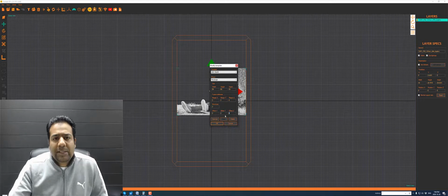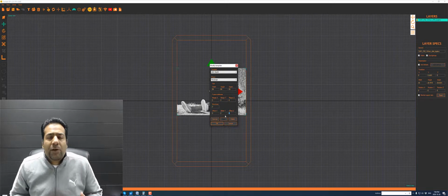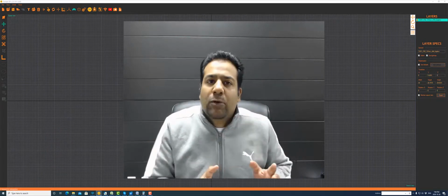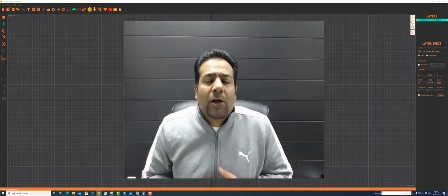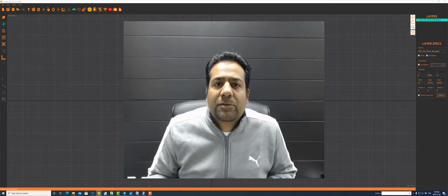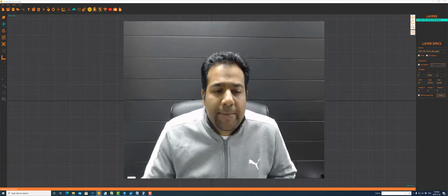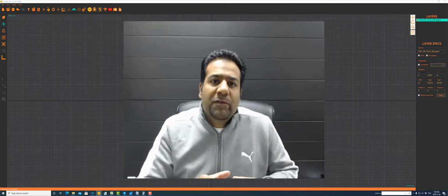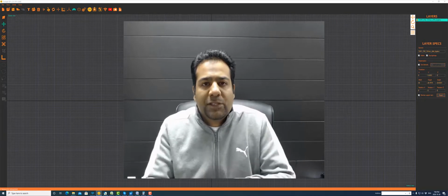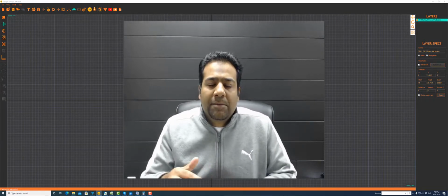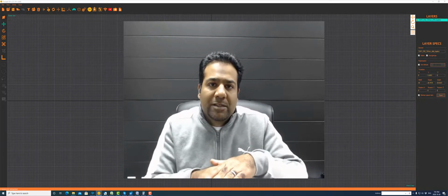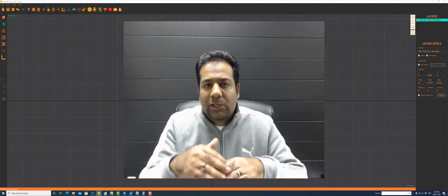Offsets. So offsets are, for example, if your laser has this issue of always burning the image off-center. So let's say that you put your crystal at the origin position of your laser, but it always burns the image 10 millimeters too high, or 10 millimeters too much to the left. Then instead of moving that crystal, I know some people create another mark on their table for where they need to position that crystal. Or if the image is not centered, they'll actually put a paper underneath their crystal to increase the height of it so that the image burns centered.